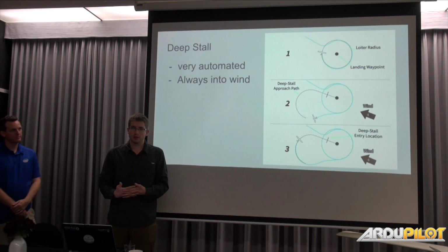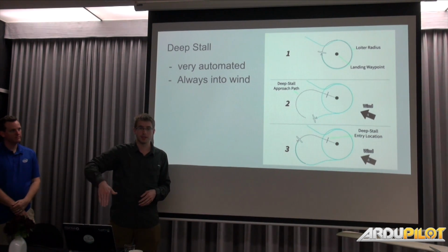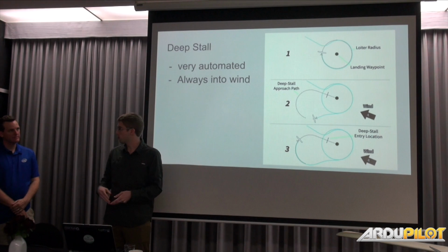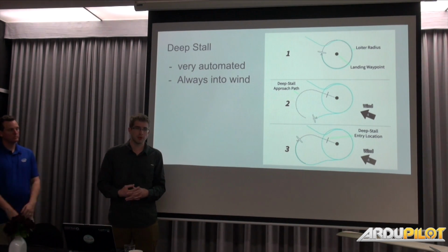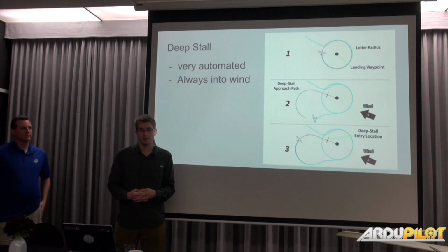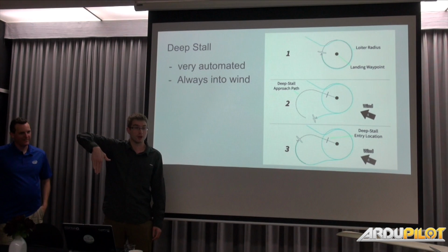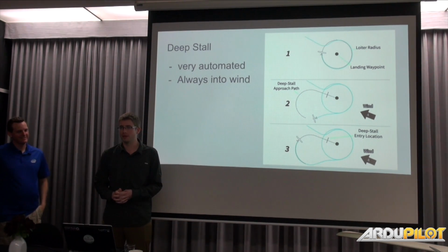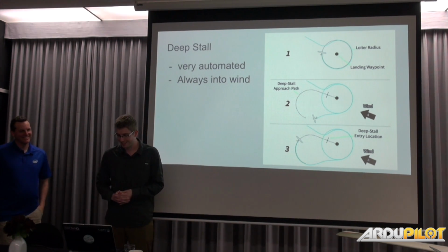Deep stalls can be avoided. It's quite easy. Put the elevator back down, the aircraft pitches down, gets a ton of airspeed very, very quickly, and it just works. You go right back into takeoff logic. So the same way you can abort any of the normal ones, you can abort deep stall landing. The main difference is deep stall has an additional parameter that says below this altitude, refuse to abort. Because first thing you do is you go full throttle and go straight down. You don't want to be doing that at 5 meters because that's one of the worst things you could be doing. That's deep parking. Something. Underground.